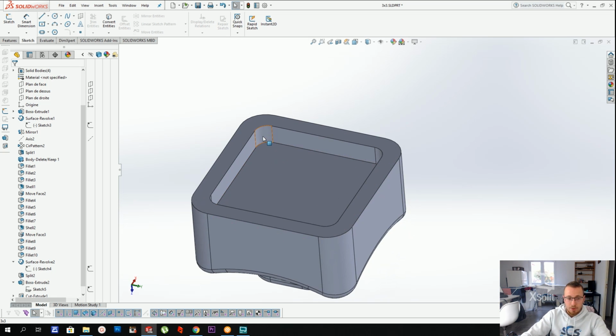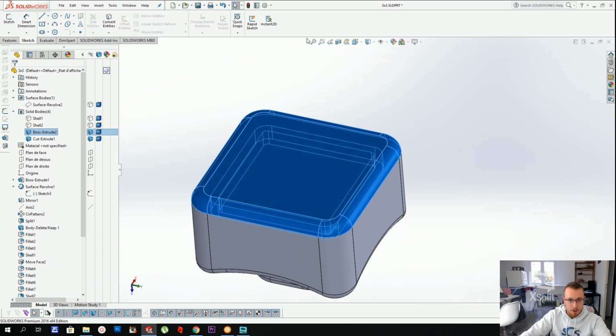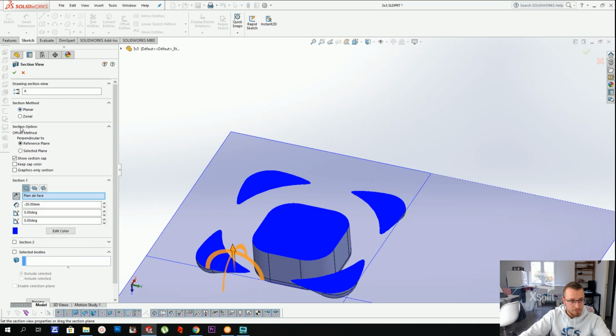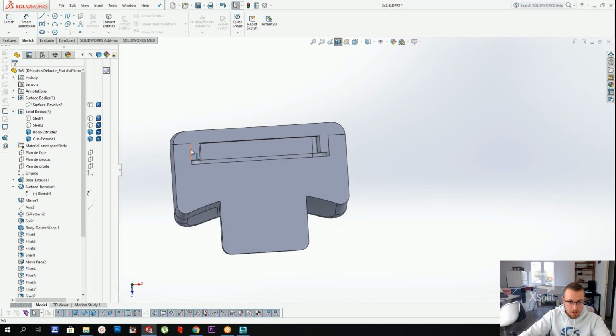But with 3D printing, there sometimes need to be tolerances, and here you will not be able to insert the cap straight out of the printer. You're going to need to add a slight tolerance, because here, let me just show the cap right there, and do a section view that goes straight through it. Here, it's going to be way too tight between these two parts.